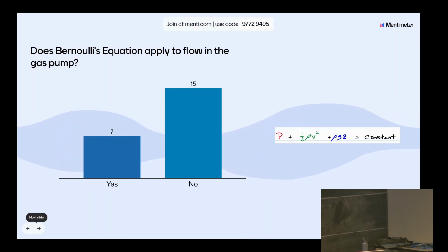So Bernoulli's equation in this form doesn't apply to flow in most pipes. We're going to extend this later on, but the reason is, like Aaron said, there are lots of viscous effects in pipes. Even in the fully turbulent case, with all that mixing that we saw, and boundary layers that are basically connecting, the flow in the pipe is dominated by viscous effects created by the pipe wall. That's what really characterizes internal flows.